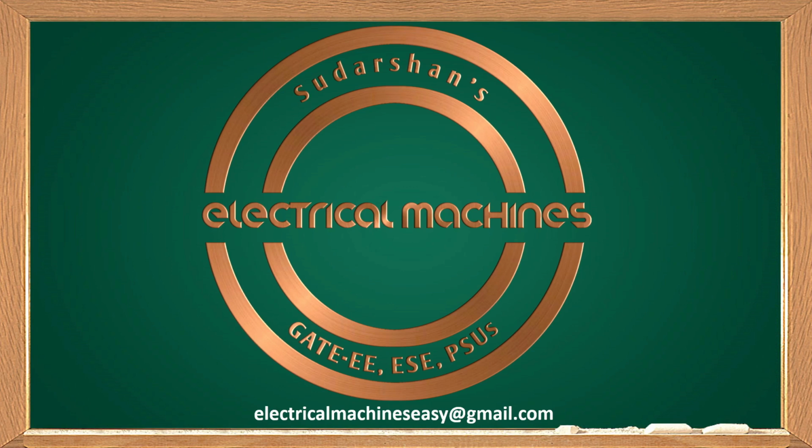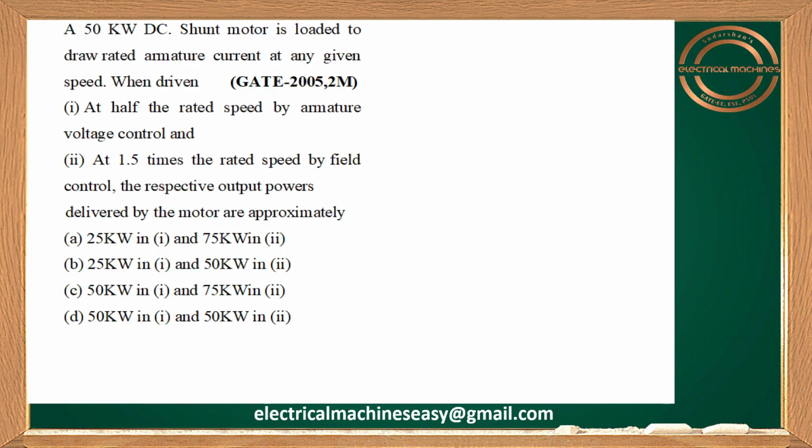In this session, we'll discuss some previous DC machines GATE questions. Let us take the first question. A 50 kilowatt DC shunt motor is loaded to draw rated current at any given speed. When driven at half of the rated speed by armature voltage control, and in the second case at 1.5 times rated speed by field control, the respective output powers delivered by the motor are approximately.